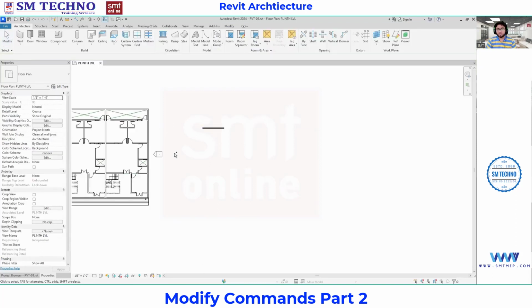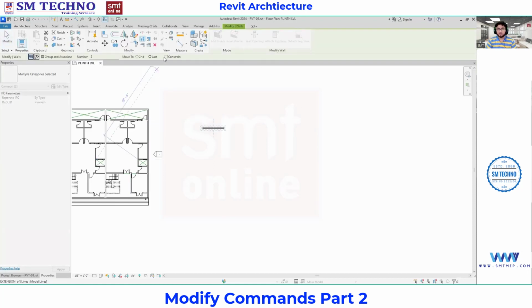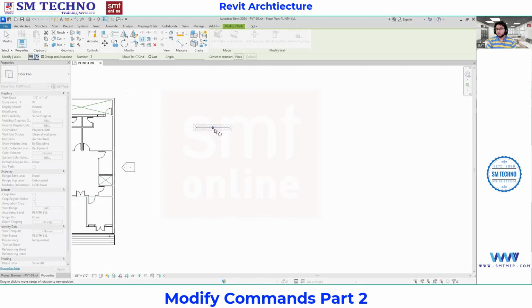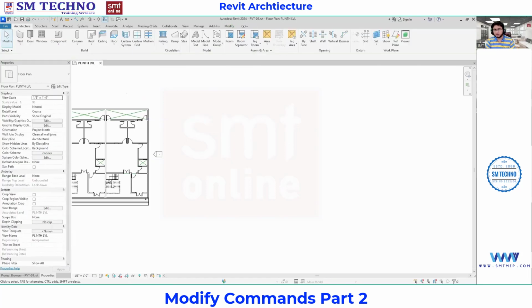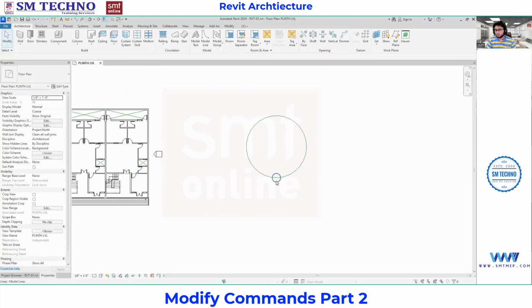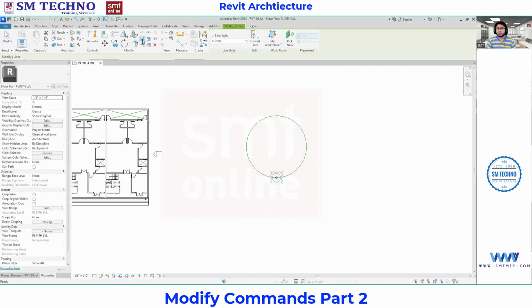Again, in the same array, we have one more option, the last one. When I'm going with array, here we have the radial option. Can you see the radial? From this, you can copy an object along with a specific reference angle. I'll go with the model line and draw a circle. Then I'll draw one object over here, for example a dining table. I'll select this object and go with the array.